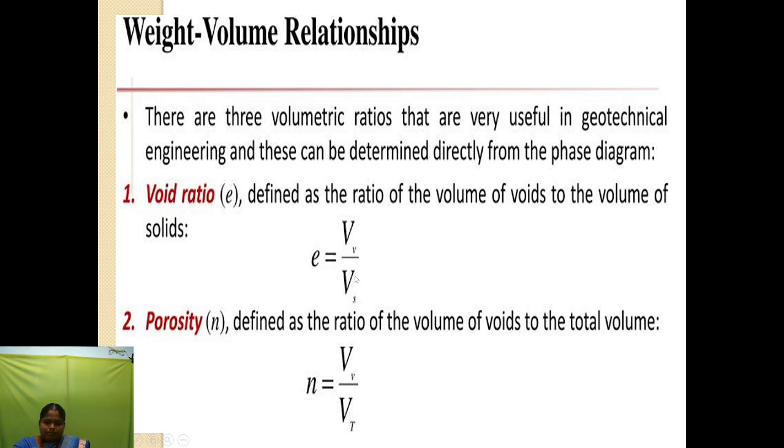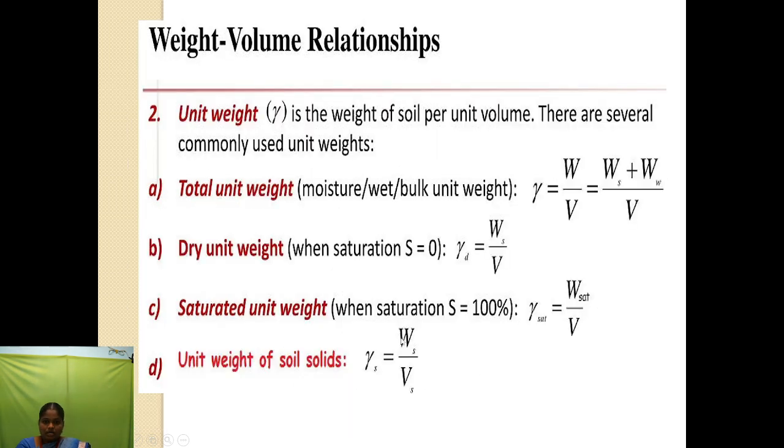So the voids ratio concept is included in the three-phase relationship. And porosity of a soil sample is defined as the ratio of the volume of voids in the sample to the total volume of soil, expressed as a percentage. The porosity is denoted by η equal to Vv by Vt.